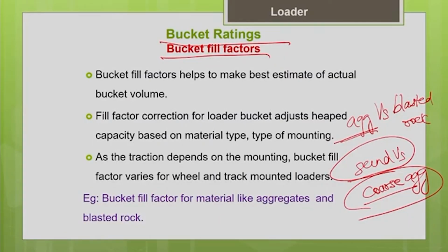So, that is why, according to the material which you are going to handle at your project site, you have to apply a correction factor to the rated bucket volume by the manufacturer. Okay. So, the manufacturer would have rated the bucket. That is the rated bucket volume, the heaped bucket volume.